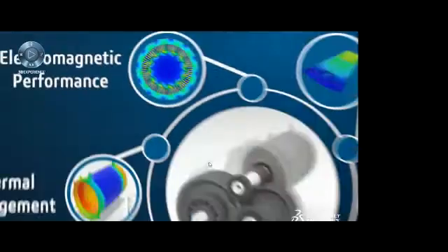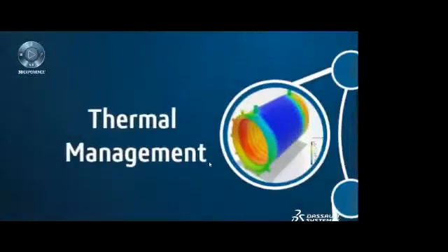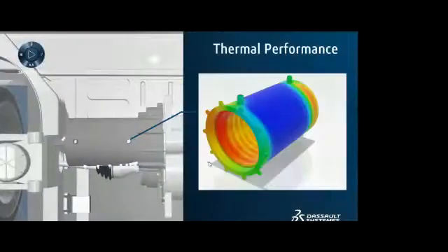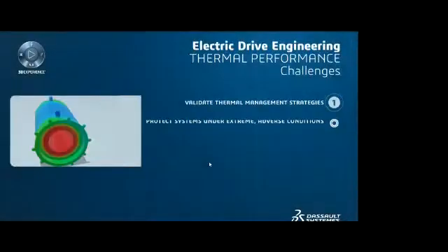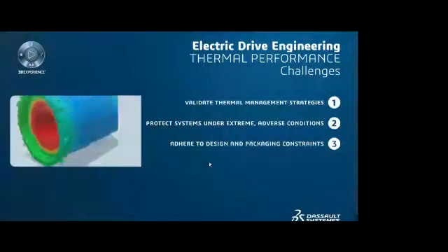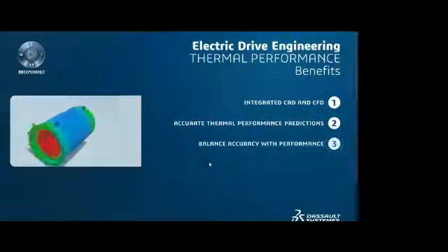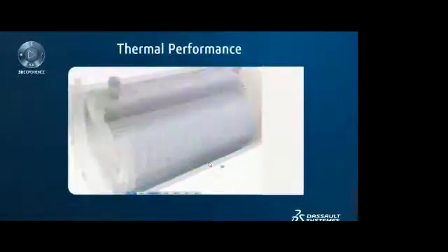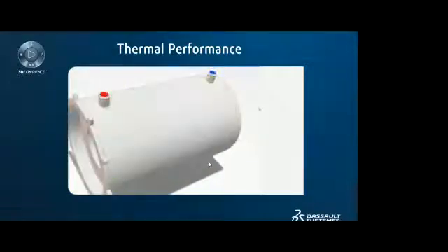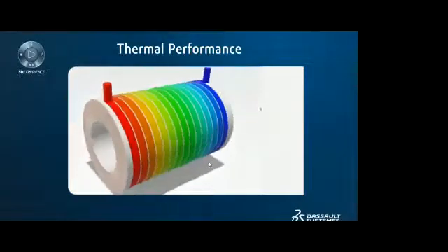The high power output achieved through electromagnetic design generates significant heat. Dissipating this heat is necessary to maximize performance and lifespan, and avoid thermal hotspots and demagnetization. The direct link between the parametric CAD model and the fluid dynamic simulation allows engineers to quickly assess the core temperatures and pressure drops in the cooling system. Engineers are also able to update and improve the design through design space exploration and optimization techniques.